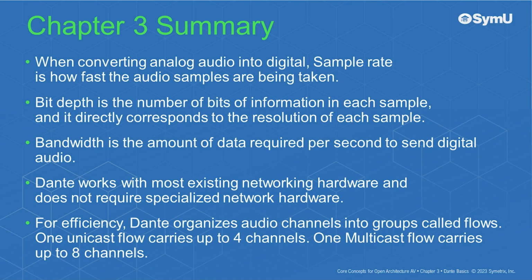In summary, when converting analog audio into digital, sample rate is how fast the audio samples are being taken. Bit depth is the number of bits of information in each sample, and it directly corresponds to the resolution or quality of each sample. Bandwidth is the amount of data required per second for digital audio to traverse a network. Dante works with most existing networking hardware and does not require specialized network hardware.